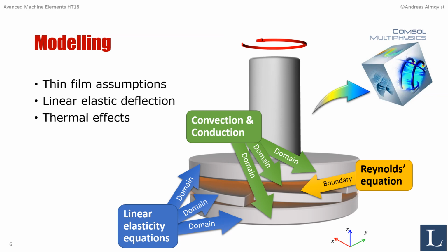And typically you would use the Reynolds equation to govern the fluid flow and the pressure buildup. So Reynolds equation is actually something that Osborne Reynolds obtained long time ago when he made an assumption of a thin film occurring in bearing situation like this.